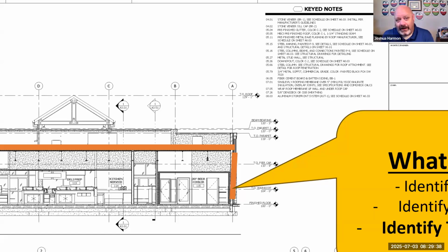So just to verify, we want to make sure we have a continuous thermal envelope, because if we leave gaps and openings, then we're just going to have places where air leakage is going to take place. Condensation is going to accumulate. We're going to have deterioration. I was talking to somebody earlier today about flashing, right? And again, that's part of this process, understanding how we create those joints and those connections.